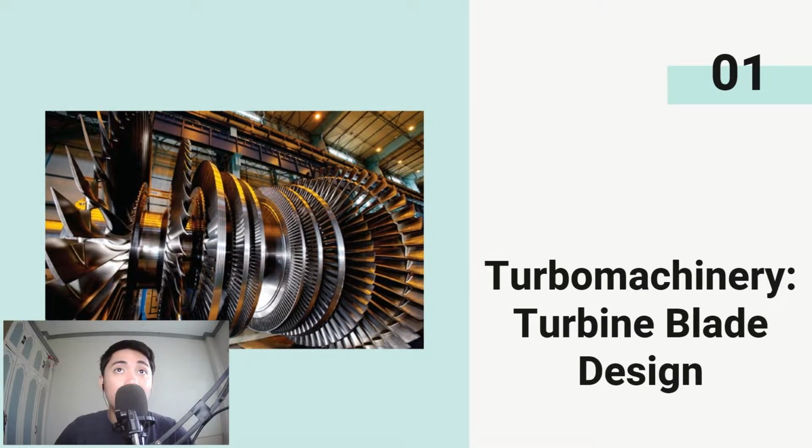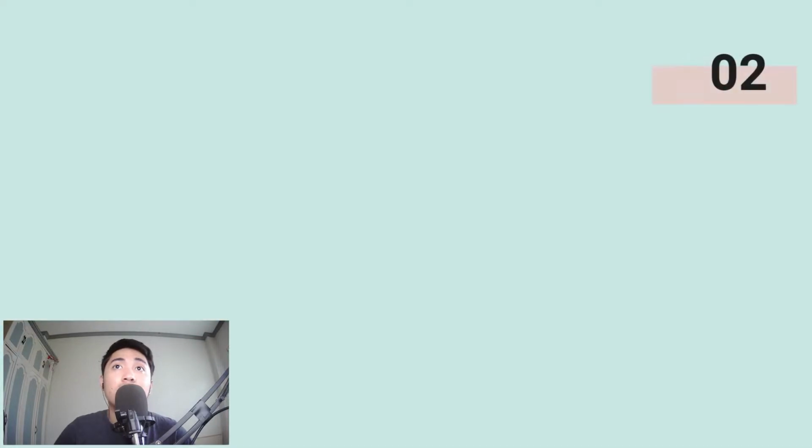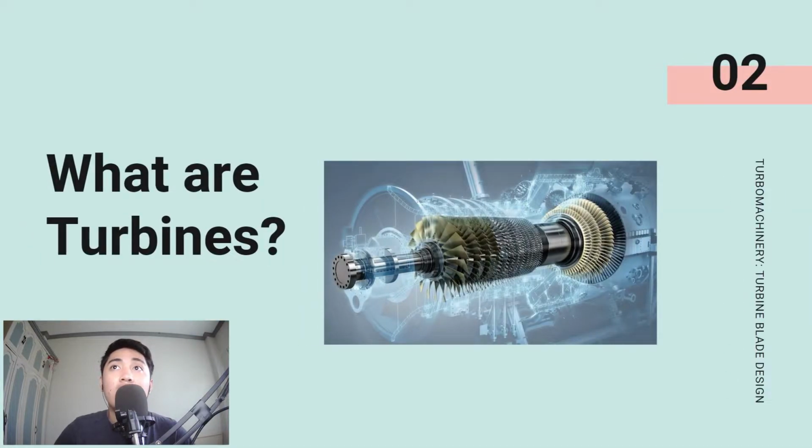Gas turbines specifically are machines composed of alternating stationary and rotating airfoil section blades. The turbine blades catch the rapid airflow and rotate to drive a spinning shaft that turns the fan and compressor at the front of the engine. The turbine essentially powers the rest of the engine, harnessing energy from the combustion chamber to maintain steady air intake